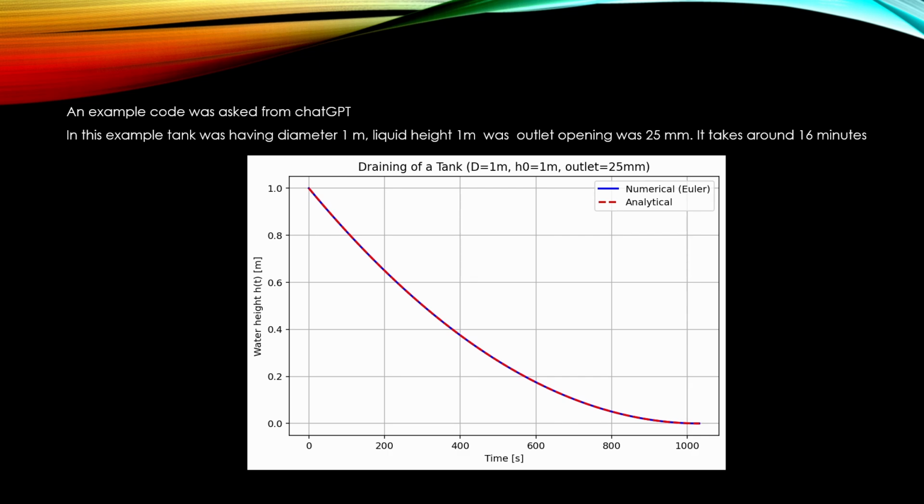And I calculated an example case in which the tank diameter is 1 meter, tank liquid height is 1 meter, and there is an opening which has a diameter 25 millimeter. And based on this result, it seems that it takes around 60 minutes to empty the tank. And in this picture you see also the analytical results, and it seems that both analytical and these numerical results are exactly the same.